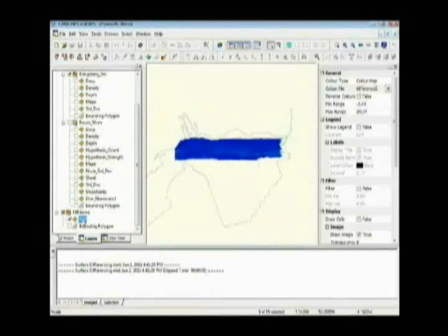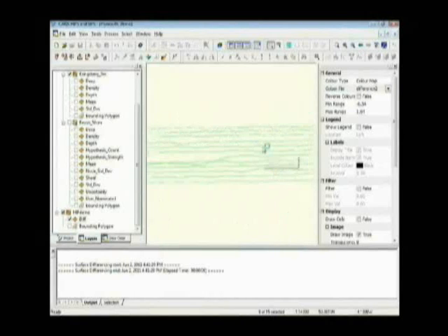Now that the surface is loaded, I'm going to go down and select the different surface, and then go up here and select Rainbow, and then change this over to difference just so we can view this surface a little bit better. Now we can see some exaggerated color parts here, which is where there's more difference between the two surfaces.